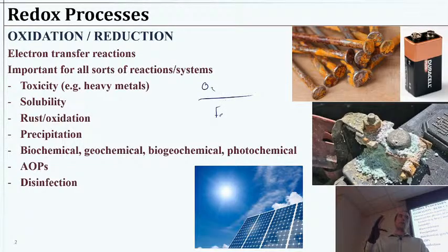The iron oxide often takes less volume than the metal, so you end up getting cracks and fissures, which open up more surface area for more oxidation, and the corrosion is a self-accelerating process so long as there is oxygen around. Things like water and salts can really encourage that, lowering the activation energy for those reactions, and bring oxygen even deeper into the material. So there are features of our solution that could enhance that.